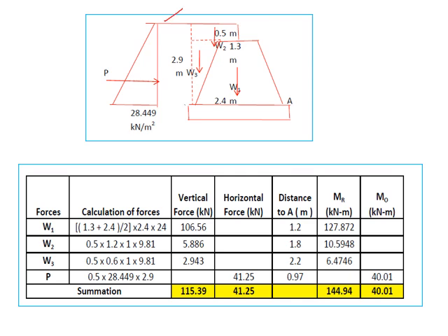So now we know that, you can already draw the water pressure diagram. Now here, when there are dam stones and the water is filled up to the maximum water level, we get a water pressure something like this. That is nothing but gamma, the specific weight, into H, 9.81 into 2.9 gives 28.449. So you can do the stability analysis for the weir.